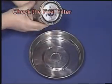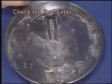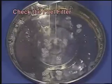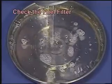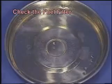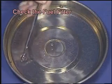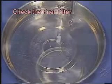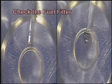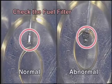You also should inspect the fault on the fuel in the filter. At this time, please check to see whether or not any foreign materials, including metallic powders or moisture, are mixed. To do so, we recommend checking the diesel fuel in a vessel using a magnet as shown on the screen. In the situation shown on the screen, there are no foreign materials. However, as shown in the smaller scene on the side, if any metallic materials are found, the filter has defects.